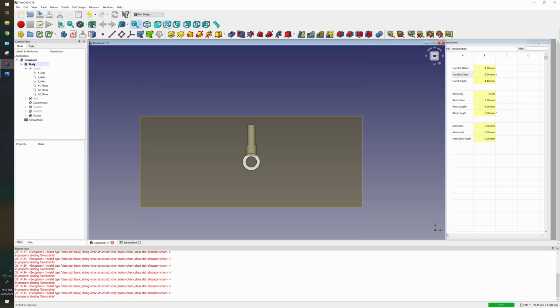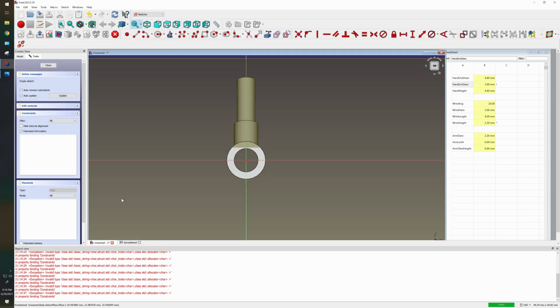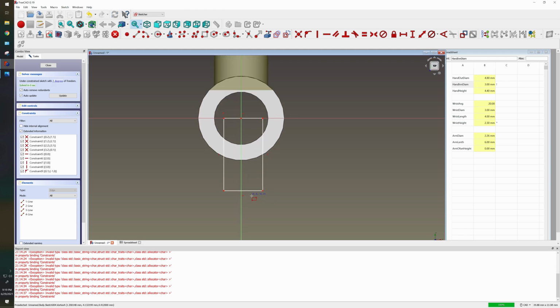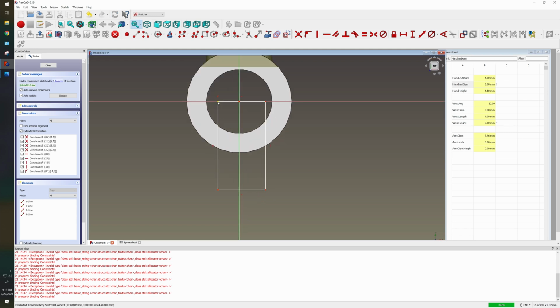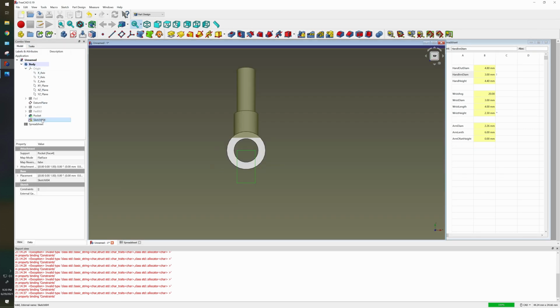Click on top view again, and we're going to add another sketch. Let's add the sketch on top of this one as well, and we'll go on top. I want to force it to here. So now we got our constraint to this guy right here, and I want to make it equidistant, so that's my favorite command. Click, click, click, and of course we want to go symmetric. Click here, and now we're dead center.